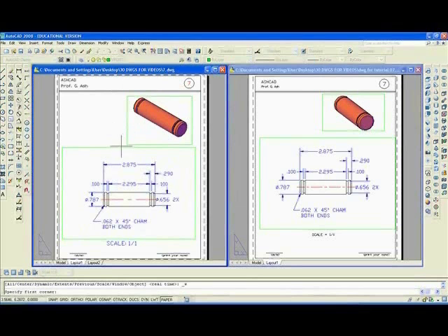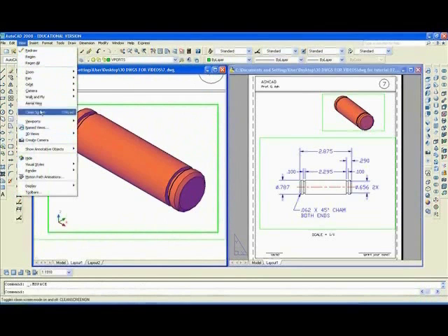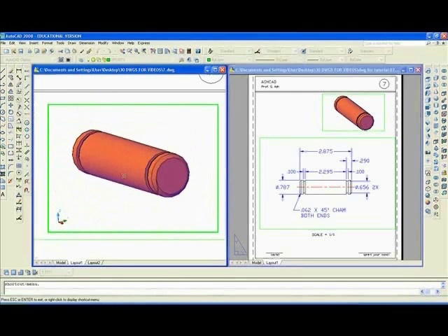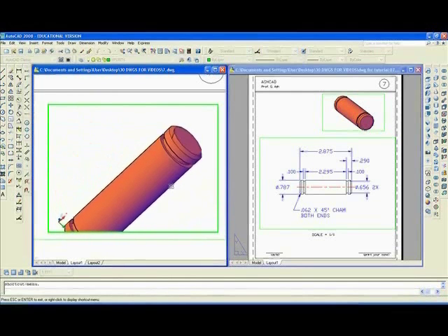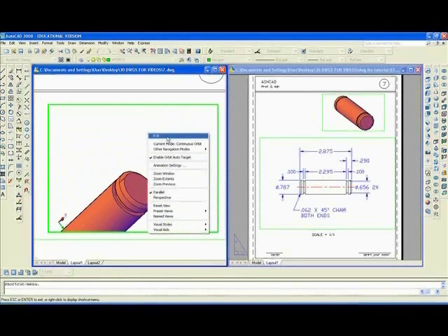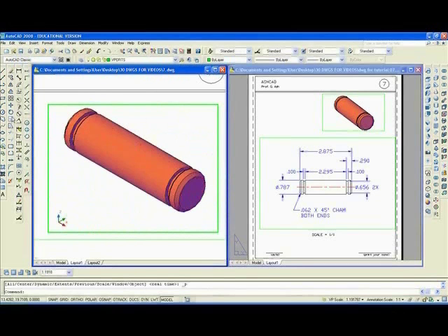Now I'm going to zoom with the window and rotate this drawing solid to see what it looks like. So I'll double click inside. I'll go to View, Orbit, Continuous Orbit. This time I'll switch it. Ooh, that's not good. I'll just turn it like that. Well, anyway, forget it. For the time being, I'll just go to Zoom Previous, double click outside,